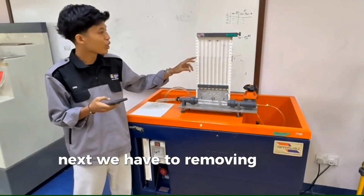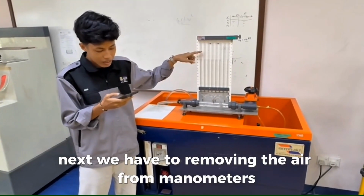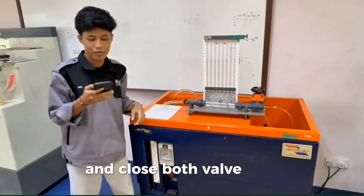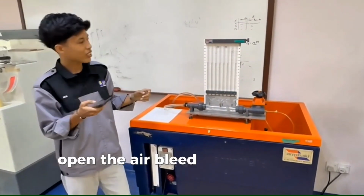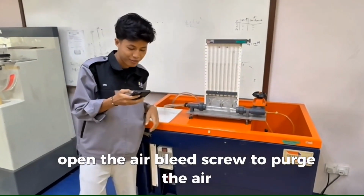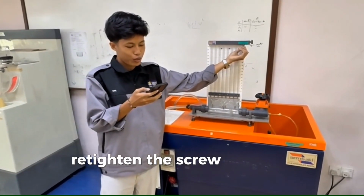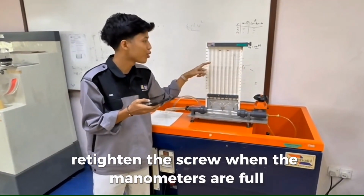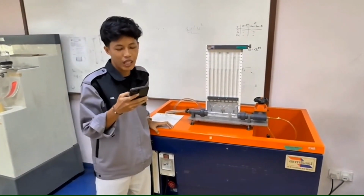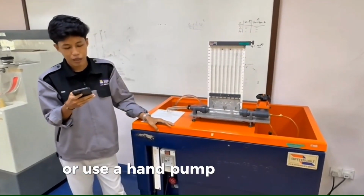Next, we have to remove the air from the manometers and close both valves. Next, open the air bleed screw to purge the air. Retighten the screw when the manometers are full. Next, if needed, slightly open the bleed screw again to adjust the level, or use a hand pump for pressure.